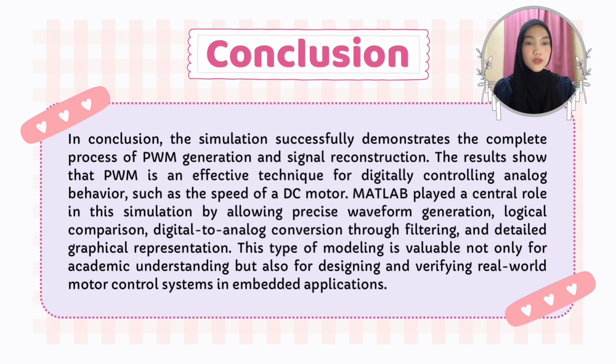The results show that PWM is an effective technique for digitally controlling analog behavior, such as the speed of a DC motor. MATLAB played a central role in this simulation by allowing precise waveform generation, logical comparison, digital to analog conversion through filtering, and detailed graphical representation.